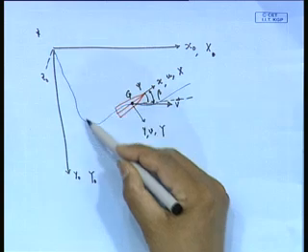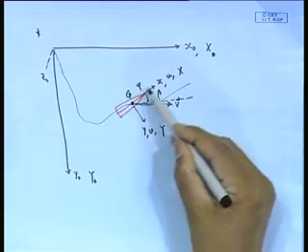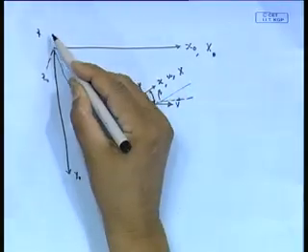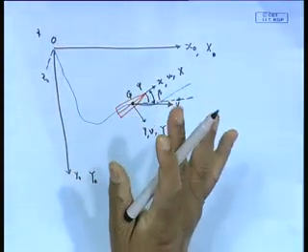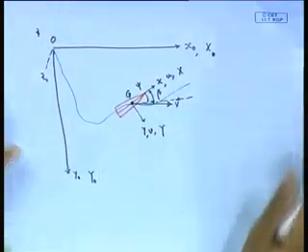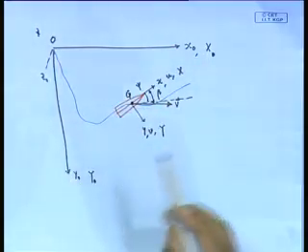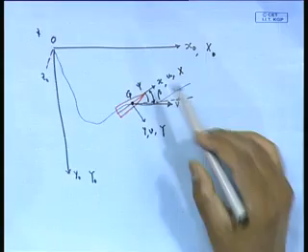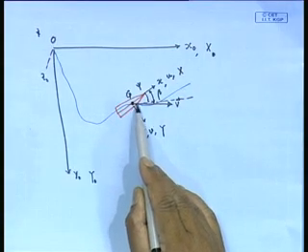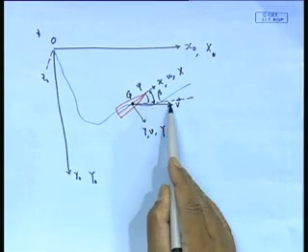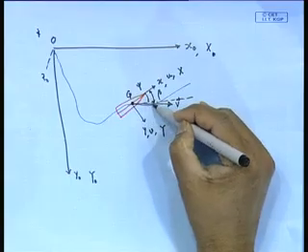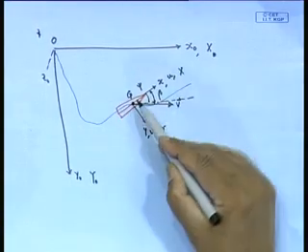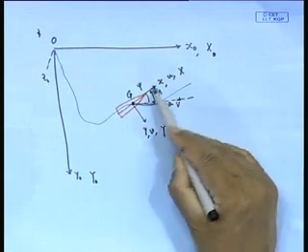Now, we need to find out this trace along with the orientation. So, we have defined an inertial system with an origin at O, which is inertially fixed, earth fixed, O x0 y0. We have a body fixed system called G x y. The body has a velocity vector v, which is somewhere on this side. Therefore, it is going with an angle of attack or drift angle beta, because it is moving this way, but its body orientation is here.